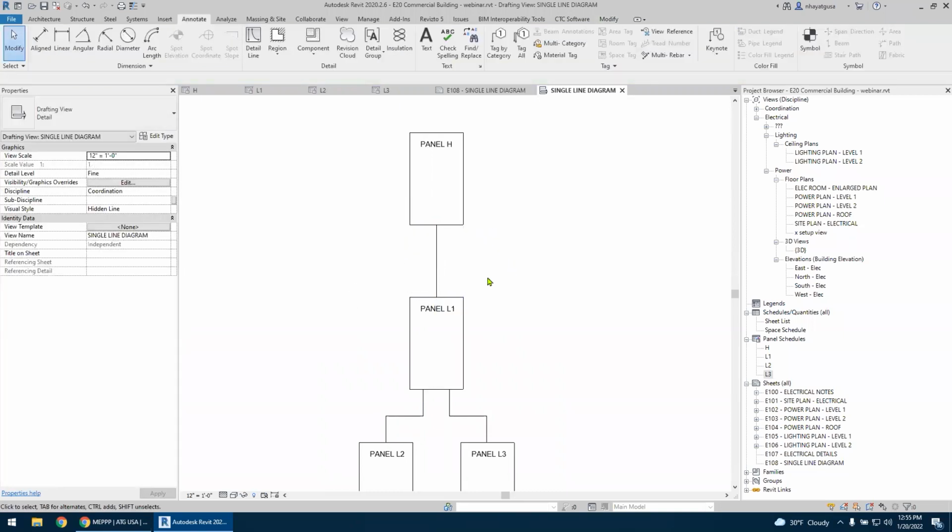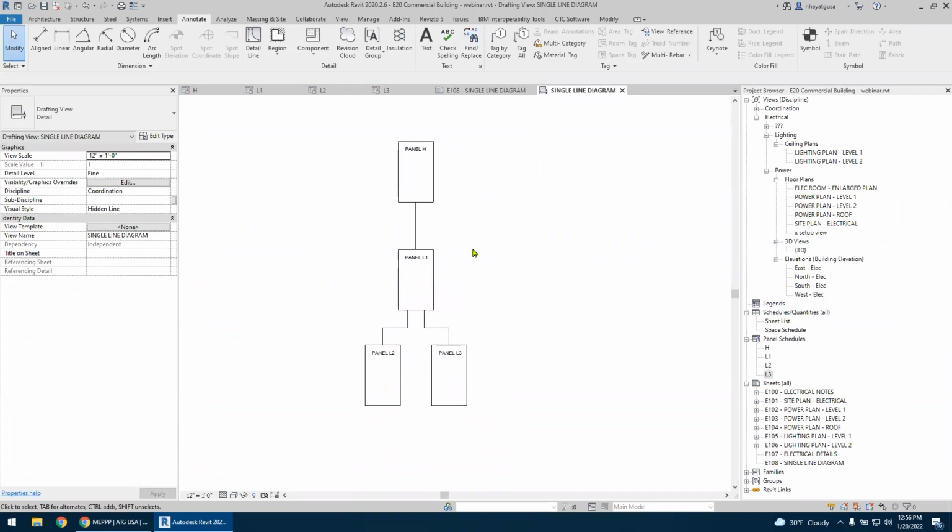What about my transformer? I got to draw a transformer symbol. There's no transformer symbol in Revit, so you have to draft it: semicircles, copy them anyway. One thing you might be tempted to do is import your AutoCAD stuff. I don't want you to import AutoCAD into Revit. It will clutter up the model because it brings in all the stuff from AutoCAD. Link it in and trace over it, and then turn them into groups.